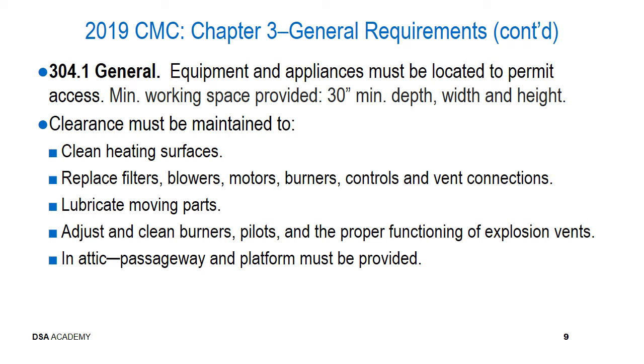Clearances to the equipment need to be provided for situations such as cleaning heating surfaces, replacing filters, blowers, motors, burners, controls, and vent connections, lubricating moving parts, adjusting and cleaning burners, pilots, and also ensuring the proper functioning of explosion vents where provided. In attics, passageways and platforms must also be provided to facilitate access.